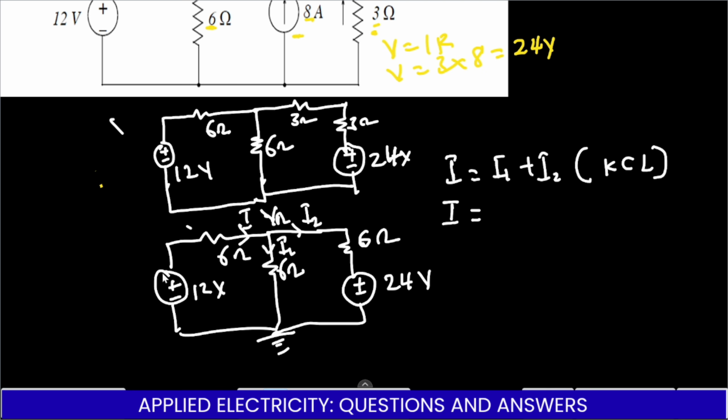Current always moves from higher potential into lower potential, right? So where it is coming from is the highest potential, and where it is going is the lowest potential. Realize that this current is moving from this junction, this I. It is coming from this side, so this is the highest potential, and then along the way there are voltages contributing. So from negative to positive, that will give us a positive voltage source. This is where it is going, that means the lowest potential, so we subtract it, minus Vn, all divided by the resistance 6.